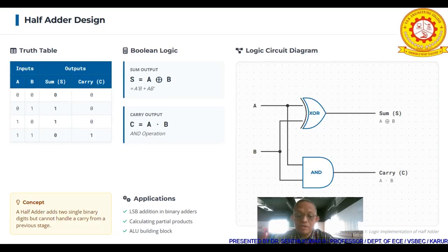Now, this is the very first circuit, called half adder design. In the half adder, it is expected to have only two inputs, and the corresponding outputs are given here. This is called the truth table. Based on the output column, identify the number of ones, and accordingly the function is described. There are two ones. I will show you how the function is described here.